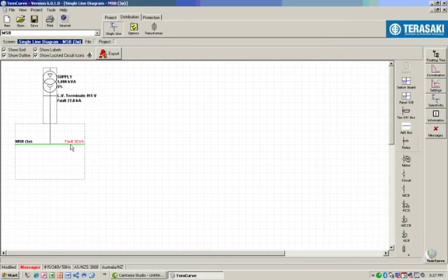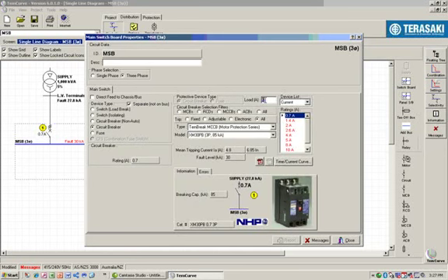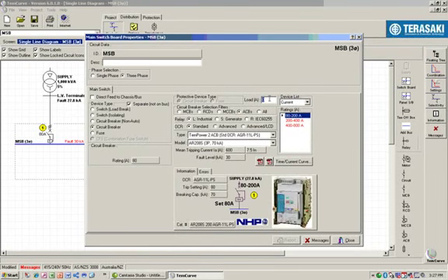You may want to have an incomer main switch, in which case it would probably be an ACB. You'd need to type in the appropriate load to do so. You can choose from a number of different overcurrent relays, which come with the NHP air circuit breakers.